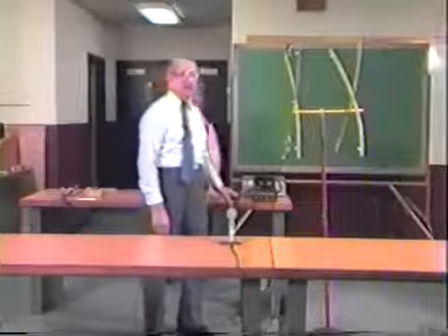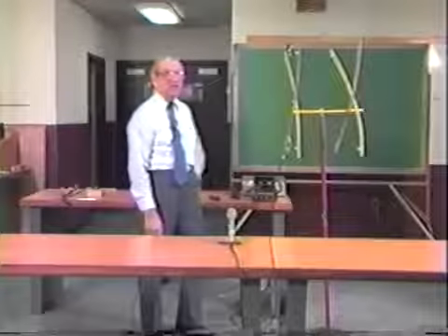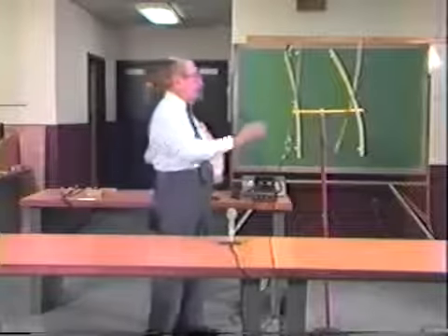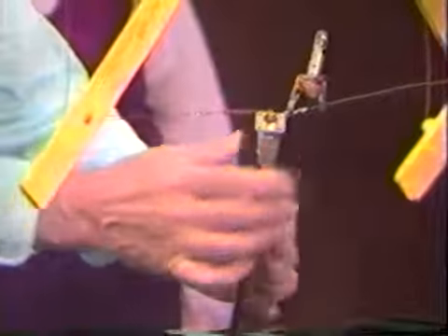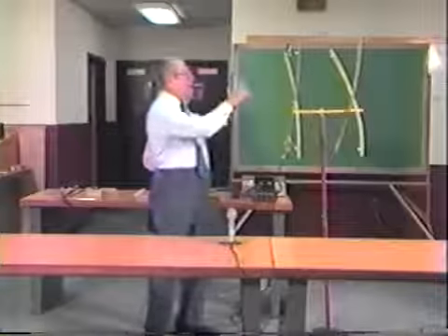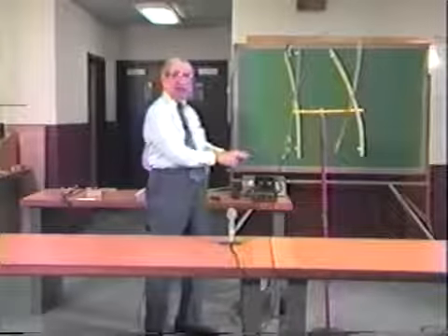Okay, we're now going to demonstrate a quad antenna. A quad antenna gives the same characteristics as the beam antenna that we showed you before. We have a quad antenna. It's fed at the base here with this coax line from the transmitter. And a quad is a full wavelength long in element length.